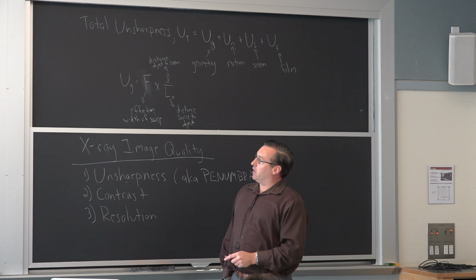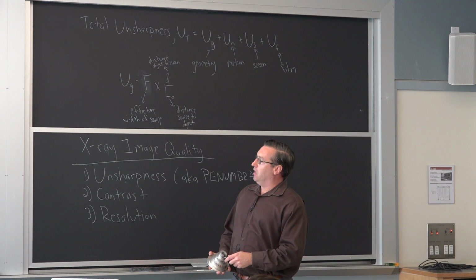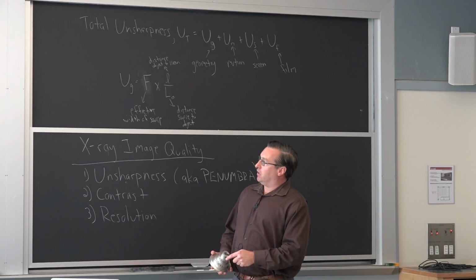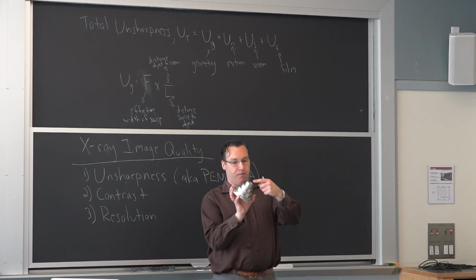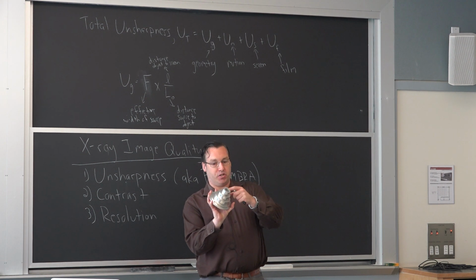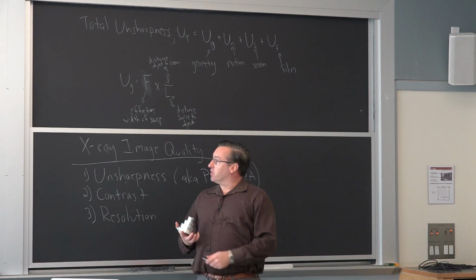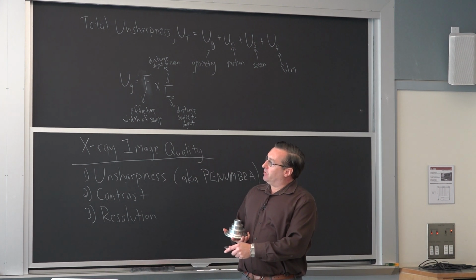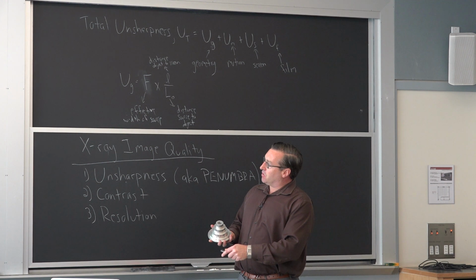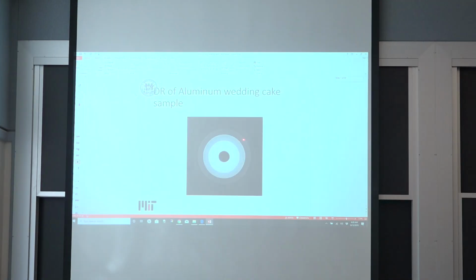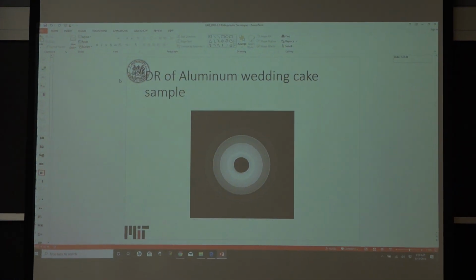One of the things you're going to see here is this sample under digital radiography. You see variations in grayscale as you go through the various layers. There are sources of noise as there's more scattering from the X-rays as they penetrate further. You're still able to see certain drilled holes and side drilled holes, but it becomes harder to find the flat bottom holes at the base layers, just due to additional scattering as you're going through the layers of the sample.